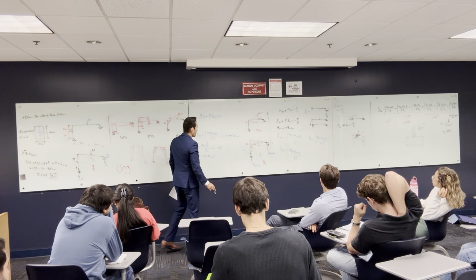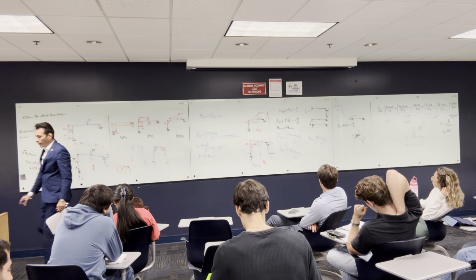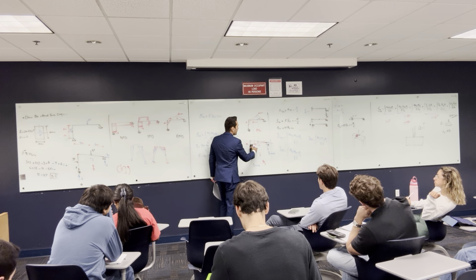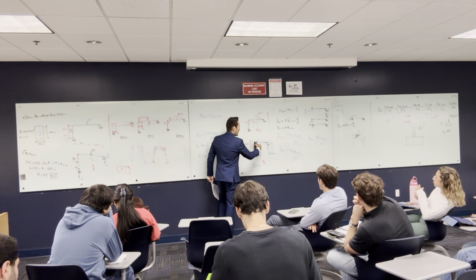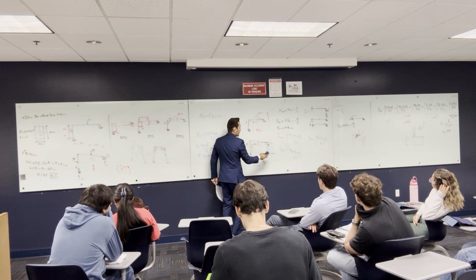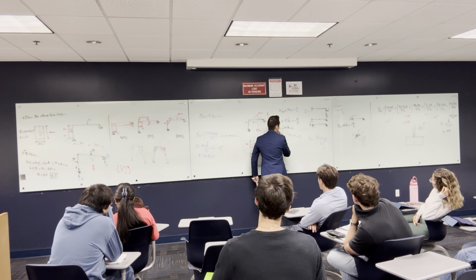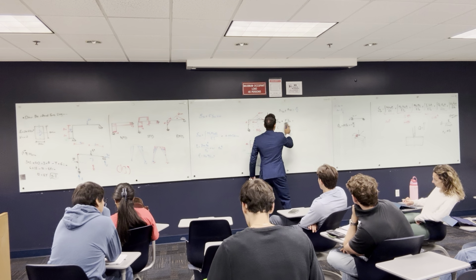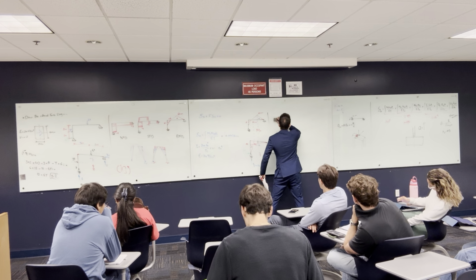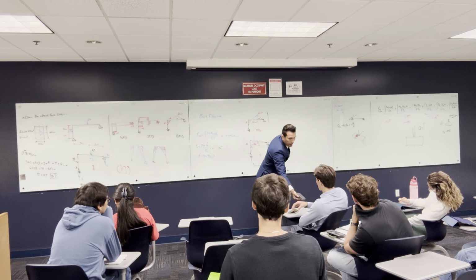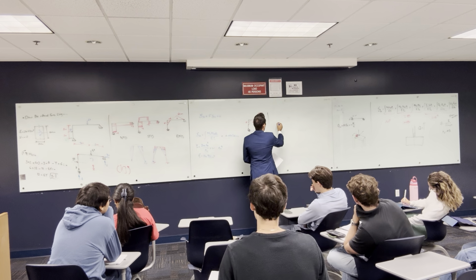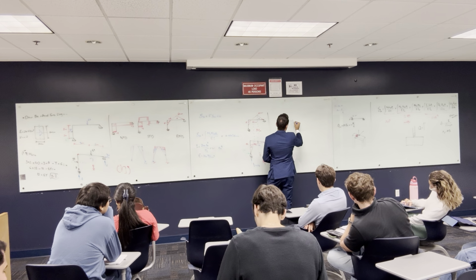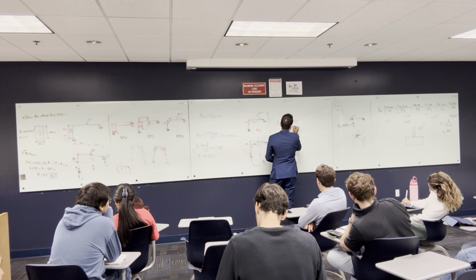The value of delta 11 is much easier than delta 1O, because you are going to integrate this with itself. You only have 2 triangles, this one and this one. If you don't know what I'm talking about, go revise the virtual work method and see how we can calculate deformations. So delta 11 is going to be the integration of M1 with M1 dl over EI.